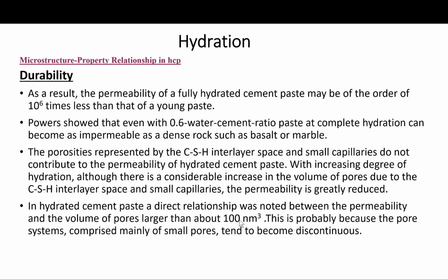So that means which pores contribute to the permeability and which do not. In hydrated cement paste, there is a direct relationship between the permeability and the volume of pores larger than 100 nanometers. This is probably because the pore system, comprised mainly of small pores, tends to become discontinuous. So again, the continuity of the pores is what constitutes permeability.